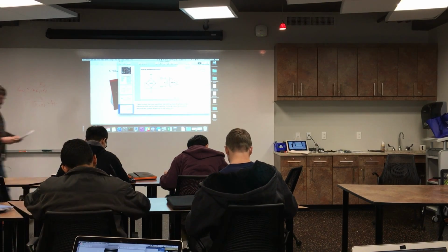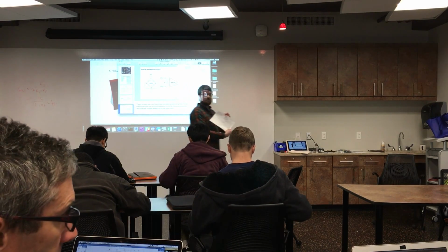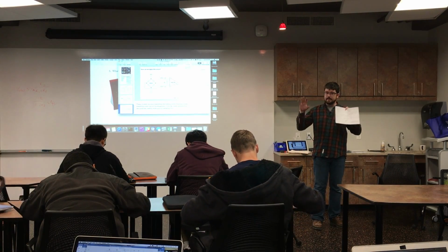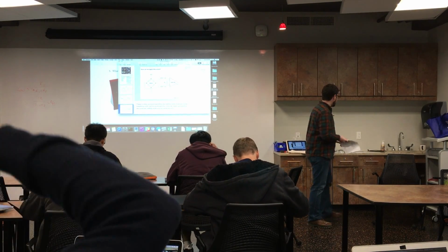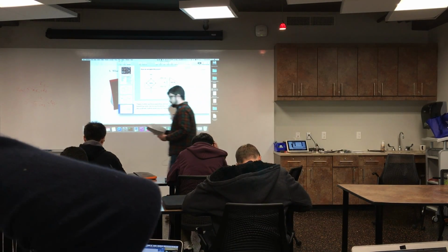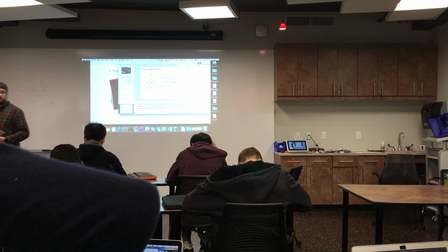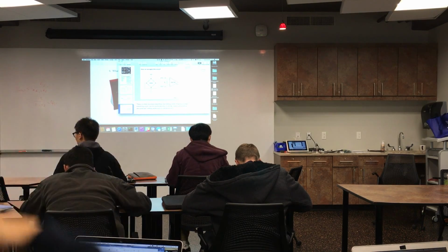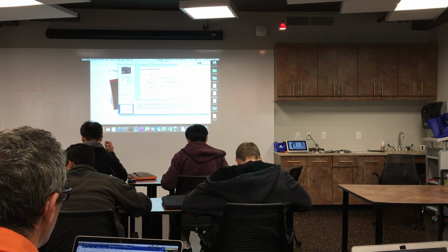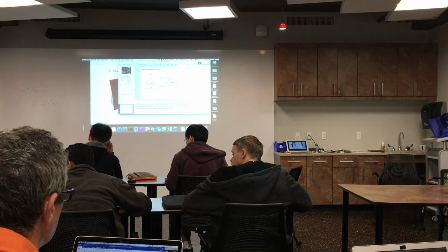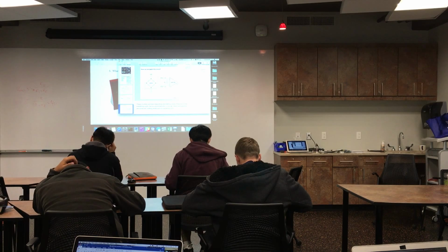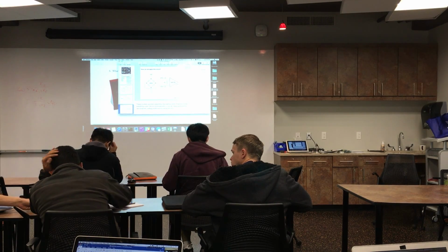And let me give you the other one. So the one I just passed out is the fail-safe circuit, which if you go too far in displacement or too high in load, locks the hydraulic piston, so bad things don't happen. The one I'm getting ready to hand out right now is the LVDT signal conditioning circuit that takes the input from the LVDT or DCDT and passes it on to the servo amplifier.